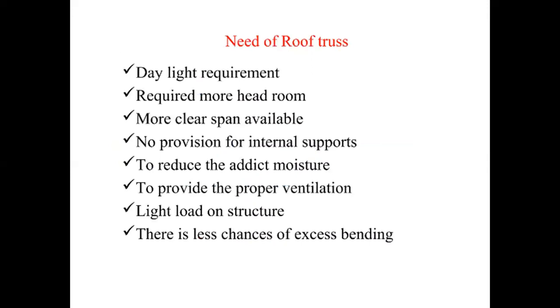And what created the need for a roof truss? The first one is the daylight requirement. If you need more headroom, a roof truss is provided, and the clear span is also more if you provide a roof truss. It doesn't require any internal support, it reduces moisture content, and provides ventilation and other advantages.